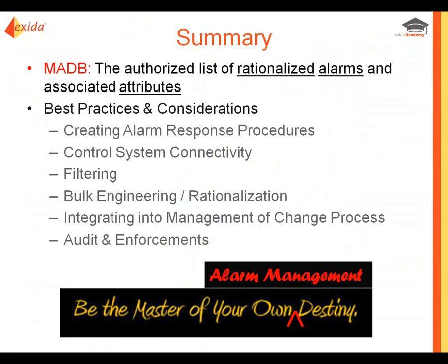So again, summary of what a master alarm database is: rationalized alarms, documenting the results of rationalization, and some of the best practices and considerations that would help make the master alarm database more useful. Things like being able to create alarm response procedures from those results, being able to connect to the control system and automatically update the control system configuration based on the results from rationalization that are stored in the master alarm database, filtering capability to allow you to home in on a group of alarms to perform rationalization for, to expedite that process and to make it easier to copy rationalization results from one alarm to other alarms that are similar.